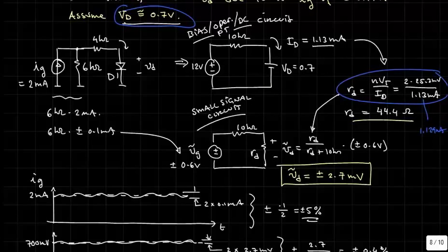That would be the more precise answer. When you plug that in, we would have had a slightly larger RD, 44.45. Point is, it would not be a significant difference. So when you're doing small signal analysis, a lot of times you don't need to have the exact operating voltage. You just want to be in close vicinity.